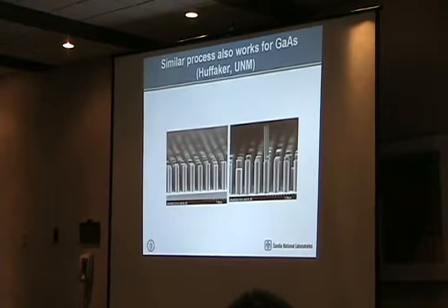Okay, and this really is determined by the mask. So if you can make the mold smaller, you'll get smaller growth. Now I use nanoimprint lithography to pattern. The nanoimprint lithography mold can be fabricated by e-beam lithography, and that's what we're doing right now. Just using, for example, e-beam lithography to start making different dimensions to make a mold, which can then be used to pattern the substrate for subsequent nanopillar and nanowire growth.